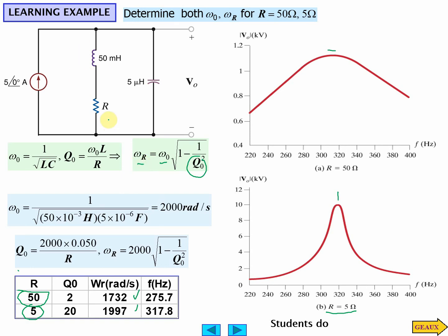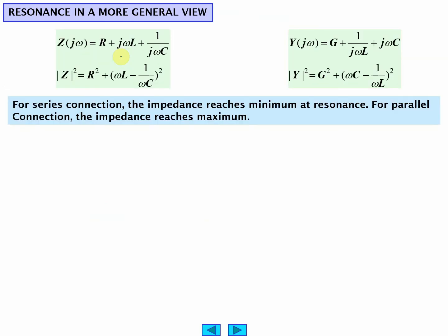Keeping the resistance low usually means fatter wires, which actually reduces the inductance. We can use ferrite cores, magnetic materials in the cores of these things, to raise the inductance.